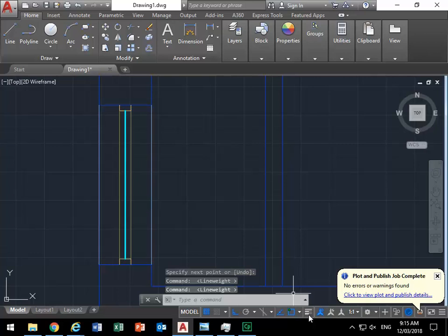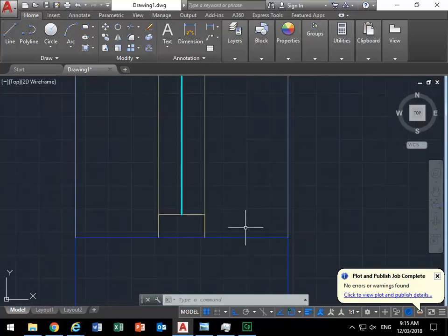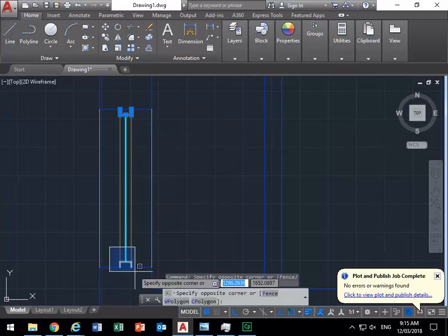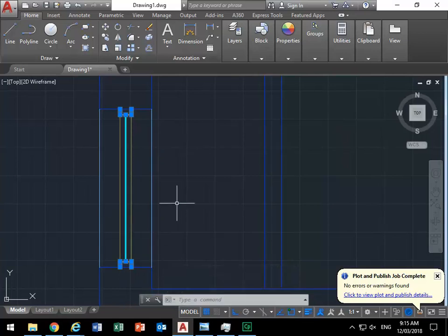and then I'm going to turn the line weights on down here just so that you can see the line weights coming from the layers now. Maybe just to make it a bit clearer what the reason is that we've got those different layers. So can you see how these parts of the window frame are the parts that are cut, and the parts either side of the glass are below the cut plane, so they need to be lighter.